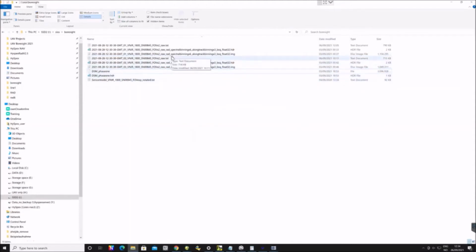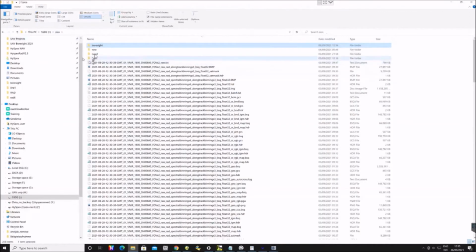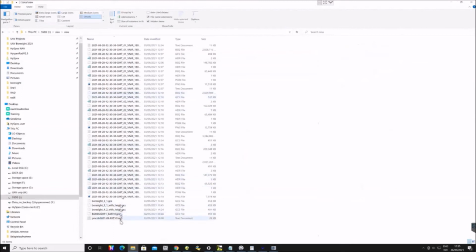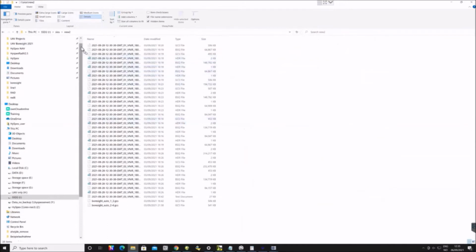Basically, it's looking to find matching files, right? Here the text file is the INS files, and the IMG files are the image files. So it was now complaining that it didn't find the matching ones. And that's actually also a case: it needs a Boresight file. I did some tests here already, so I have a dummy one with just zero parameters.